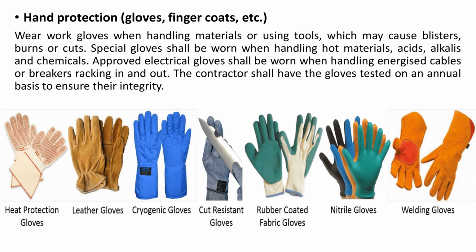Special gloves shall be worn by workers who are handling hot materials, acids, alkali and chemicals. Approved electrical gloves shall be worn when handling energized cables or breakers racking in and out. The contractor shall have the gloves tested on an annual basis to ensure their integrity.